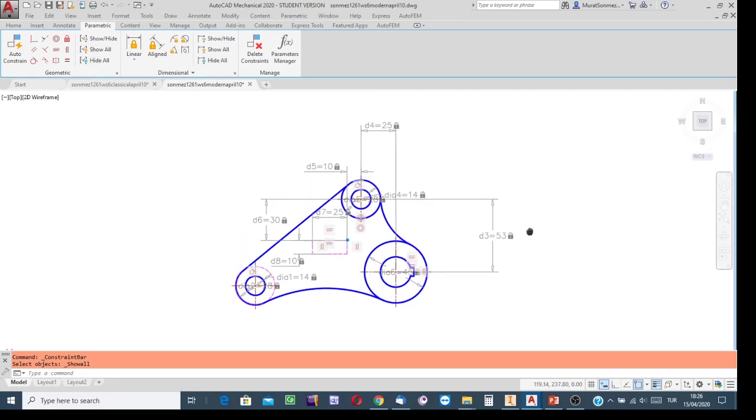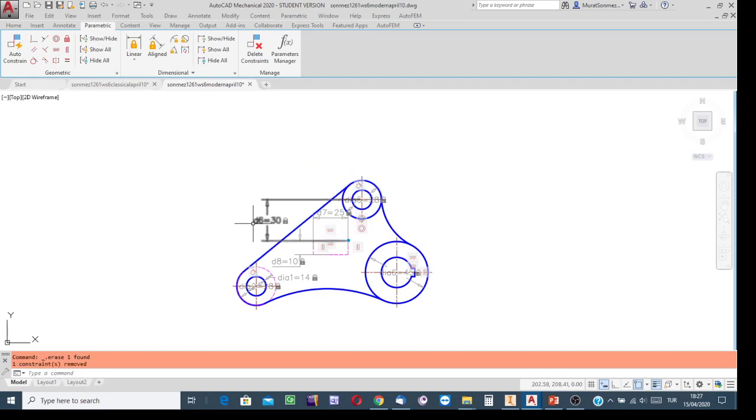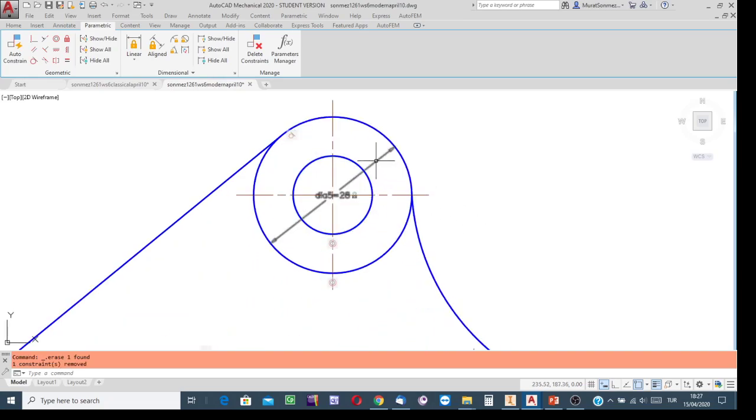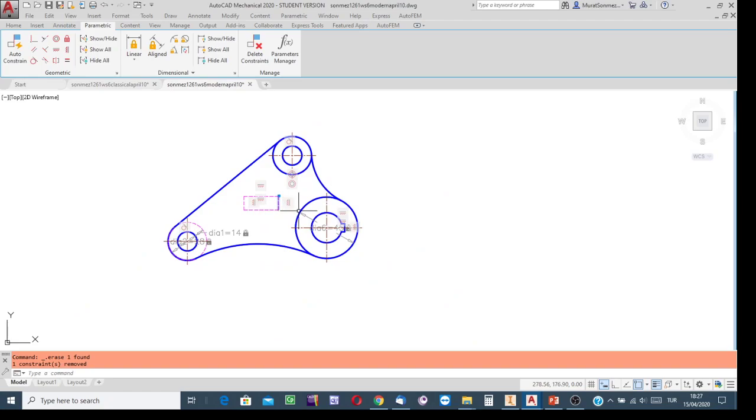Okay, and then to be able to satisfactorily resize the projection, the thing to do at the beginning is to bring the cursor onto a dimensional constraint, click, and then delete it, pushing the Delete button. Well, if you do not delete the dimensional constraints, you cannot resize the projection, because these are constraints, and those will prevent the software from changing the size of the projection. Selecting the dimensional constraints and deleting them, pushing the Delete button. It is a common deletion technique, you know.